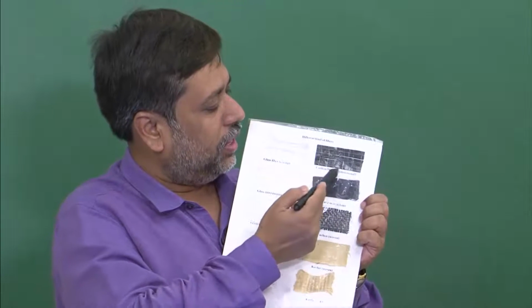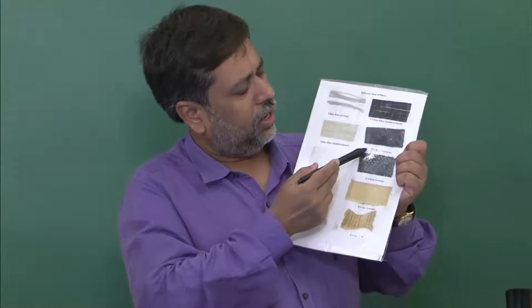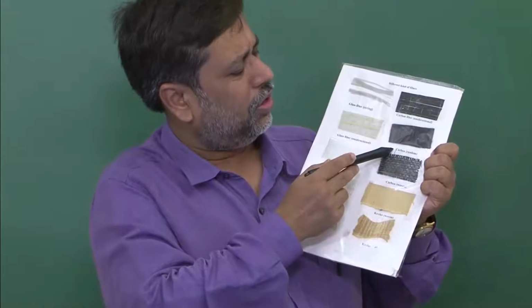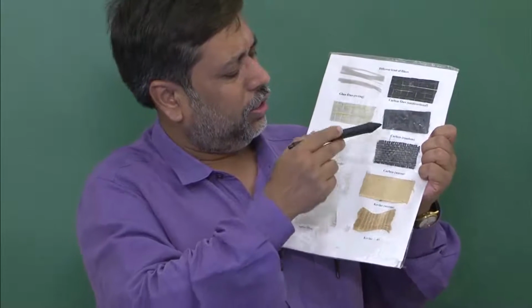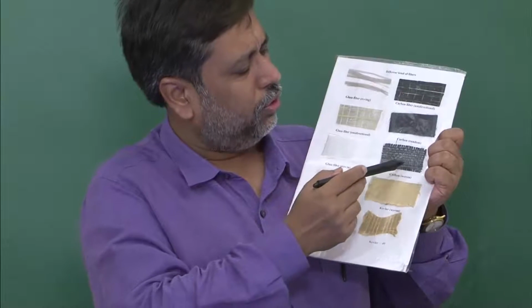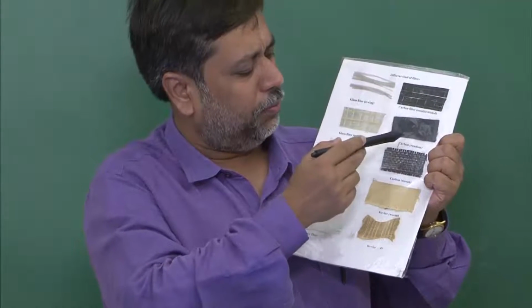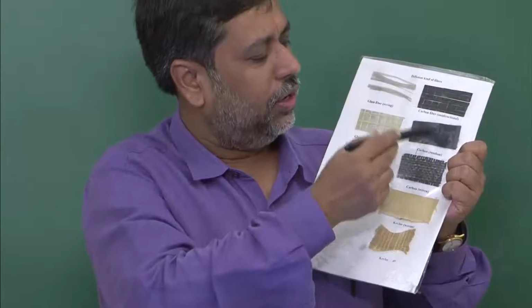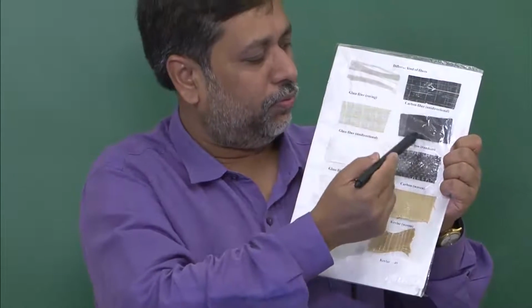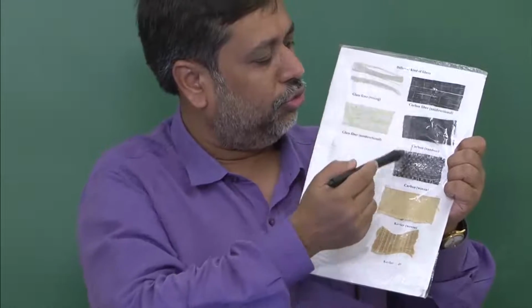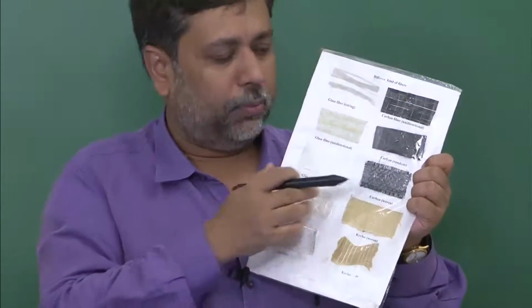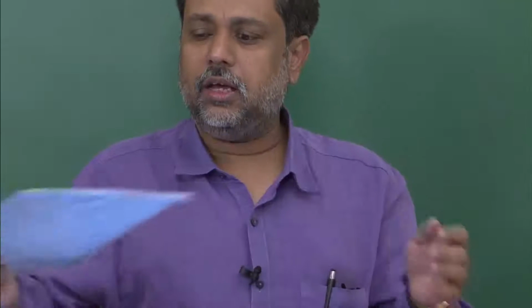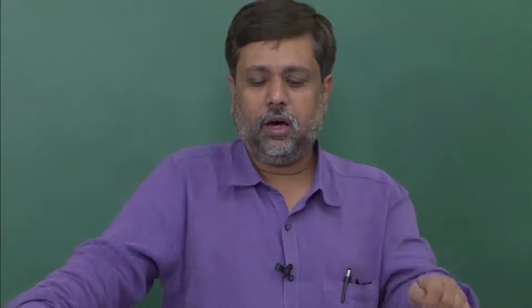This is unidirectional fiber, and then you can have carbon fibers in a woven form, for example, or in cross plies or prepreg forms, random orientations, etc. So these three, 1, 2, 3, are examples of carbon fibers. Just like GFRP, you can actually make carbon fiber reinforced composites.